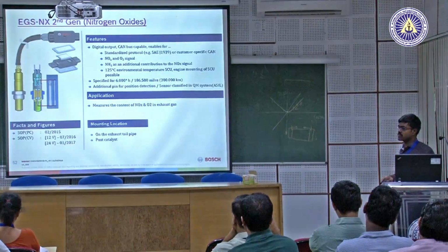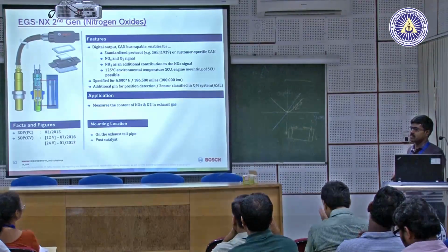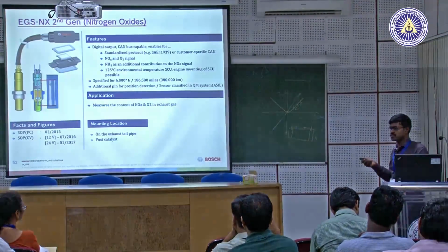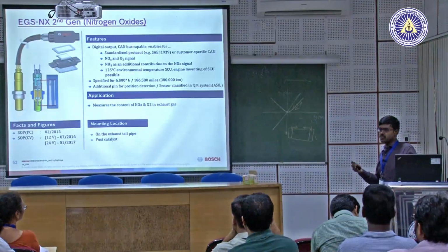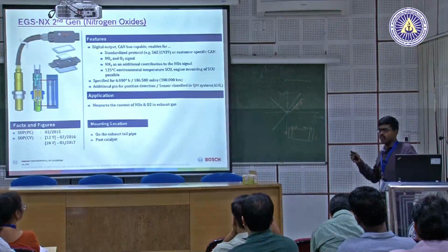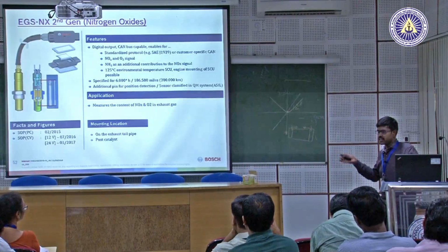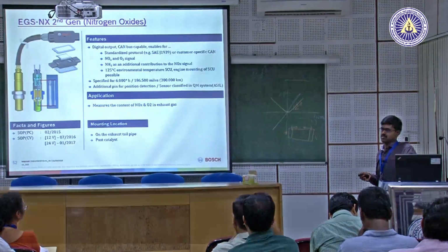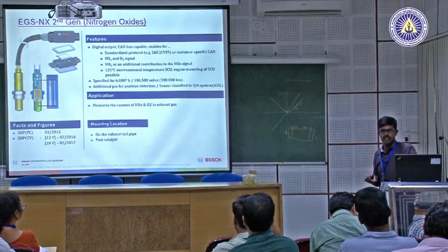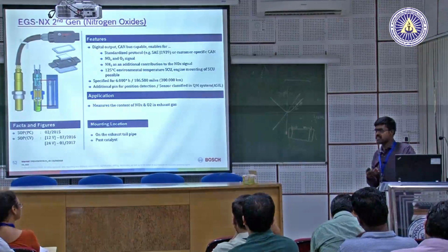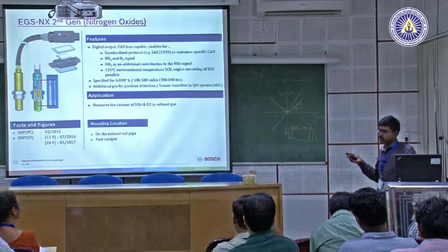And next one comes nitric oxide, nitrogen oxide, or NOx as we call it. As a byproduct of exhaust, you have these nitric oxides also. With emissions becoming stringent, we have to reduce the hydrocarbon content and the carbon monoxide content emitting out of the exhaust, because CO2 is not very harmful, CO is very harmful as you know. Okay. Same thing with hydrocarbons, they are harmful, and the main legislations are coming out because of these HC and CO to be reduced.